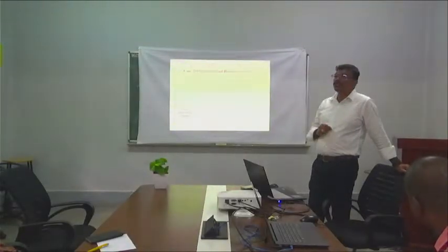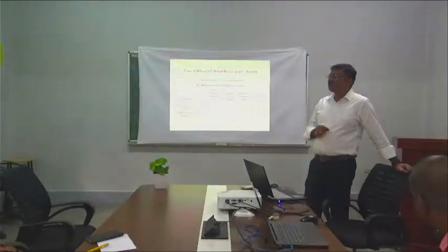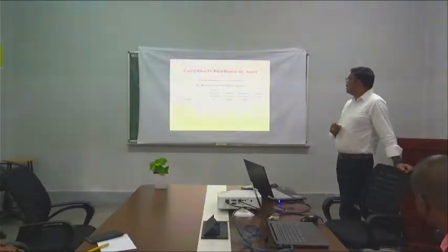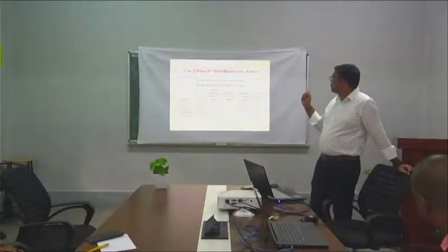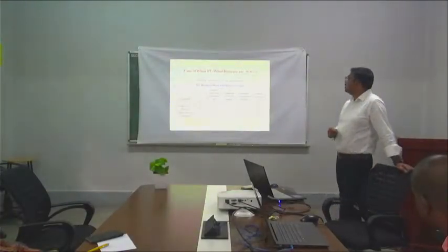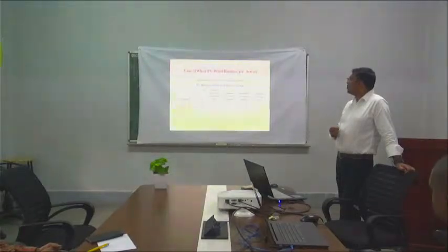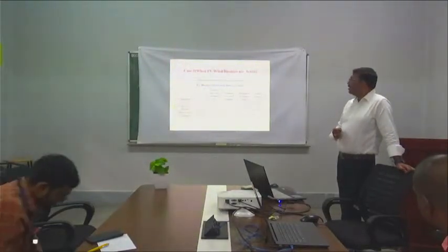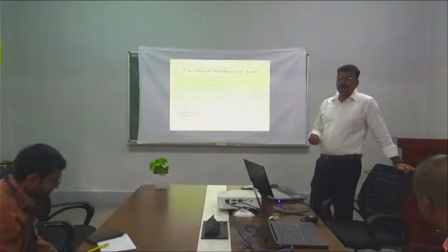Wind turbine, how many hours? Annual hours of operation we can also see here. Minimal electrical output. Capacity factor also we are going to calculate. The capacity factor for the solar PV system is 12.5. It is supposed to be more, actually it is less here. Wind turbine 26.3 and biomass always will be more, 40.2.